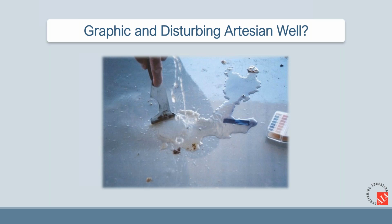And so that causes people to pause because, again, I'm changing the way that we think about moisture and concrete and how they relate to one another. Concrete, again, is very fascinating. It will take moisture from wherever it can get it. It will hold on to it, and it will release it at a slower rate than which it obtained it. So in this particular instance, we know we're not touching dirt. We know we don't have any plumbing inside of a pan deck.